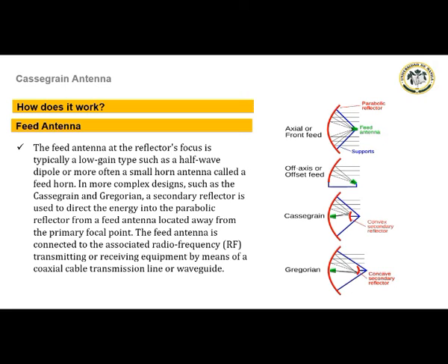The primary reflector is a paraboloid, while the shape of the convex secondary reflector is a hyperboloid. The geometrical condition for radiating a collimated plane wave beam is that the feed antenna is located at the far focus of the hyperboloid, while the focus of the primary reflector coincides with the near focus of the hyperboloid.